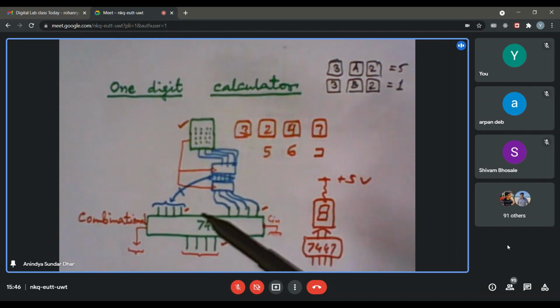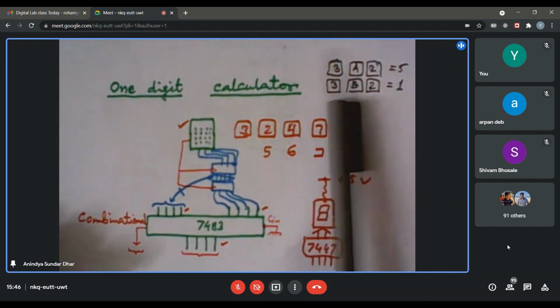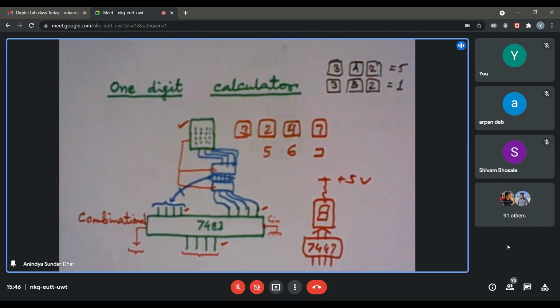Okay, so that is the small thing, but as I said, I will also give you some hints about that. At that time, you will require 3 such 4-bit registers, because you need to store the operator at that time also. If you press 3 keys successively, then you will require 3 4-bit registers. So this much I am telling for those who complete it very quickly and go for the next experiment. And you may download in between the data sheets for 74283, that is the 4-bit adder, and 74273, and if you wish 374 also, that is an 8-bit register with master reset, or 8-bit register with tri-state facility.